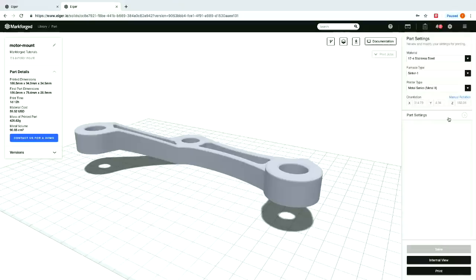So that's about 64 thou, so 0.064 inches, I believe. Yeah, so the idea with metal parts now is post-machining is done to add that extra little bit you need to hit a tolerance on a part that needs to be more precise, and then getting a really nice smooth surface finish on parts that you print.